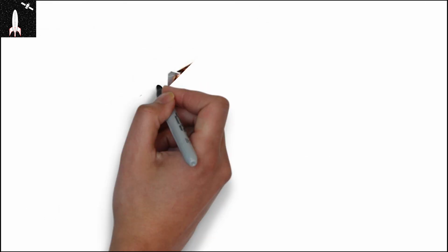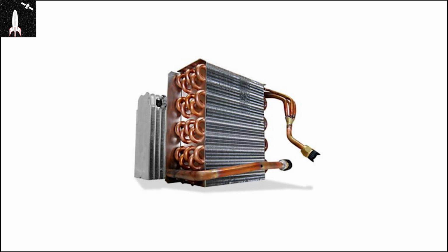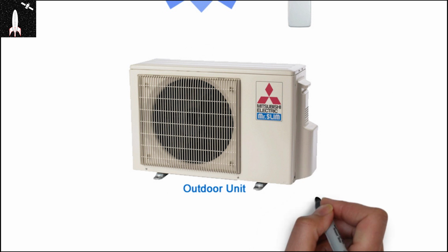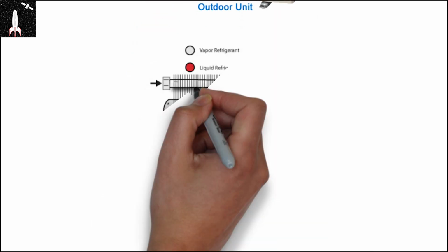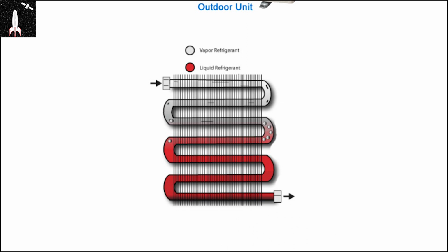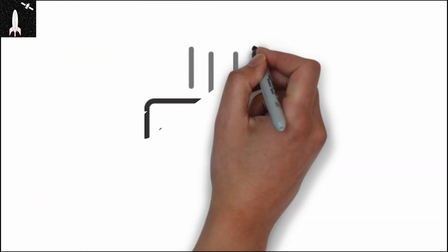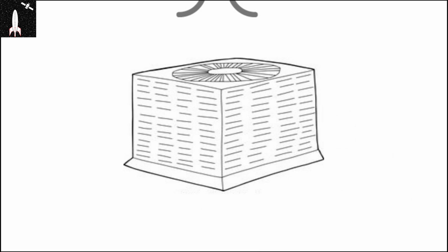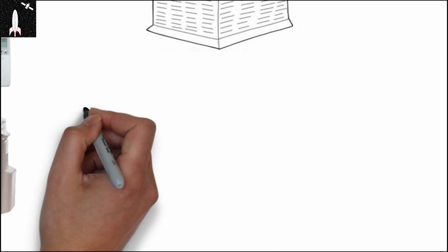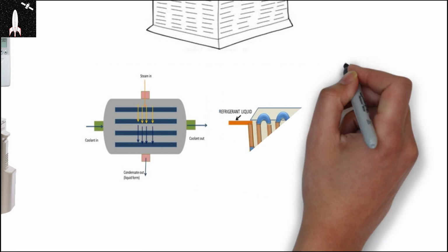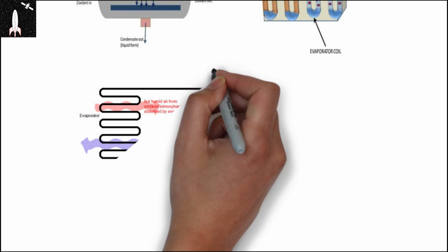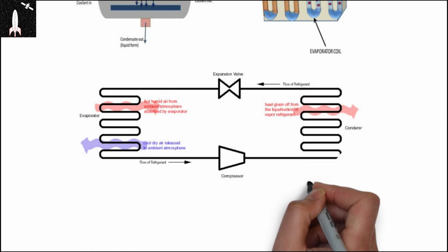The air conditioners we use are generally made up of two connected coils known as evaporator, which is inside the room, and the condenser, which is kept outside. There is a continuous flow of refrigerant fluid within these two. The main function of the evaporator is to maintain the temperature colder than that of the room, while the condenser maintains the temperature hotter than the surroundings. When the AC follows these two functions, the continuously flowing fluid will absorb the heat in the room with the help of the evaporator and push it out through the condenser. This is the principle that is used by the AC.